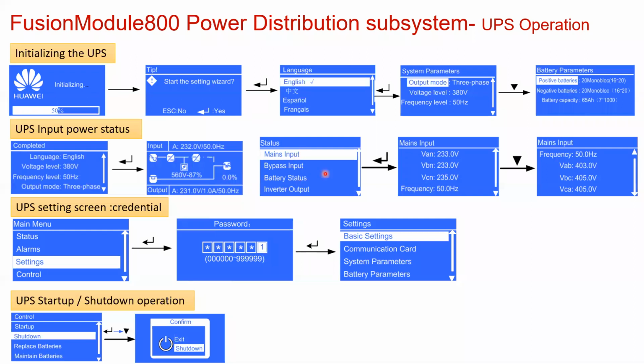When we operate this device, it gives you all these ratings, like what my balanced output is to the rack level, because in the rack we have the critical IT equipment, which needs static power. Whatever fluctuations come are in the raw power level. Once it comes through the UPS, it is already filtered power, and you have safe power for your IT equipment.